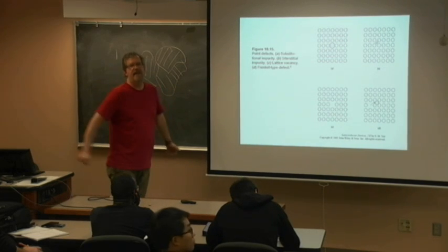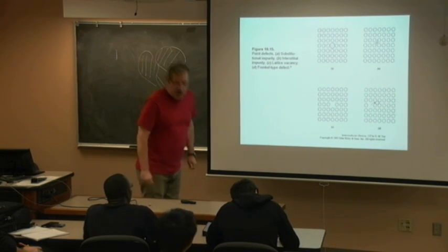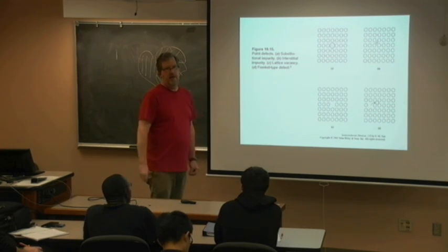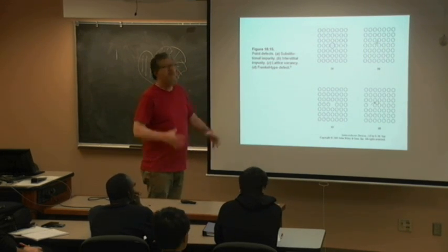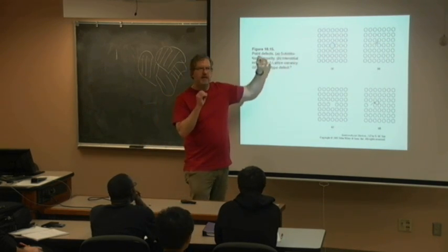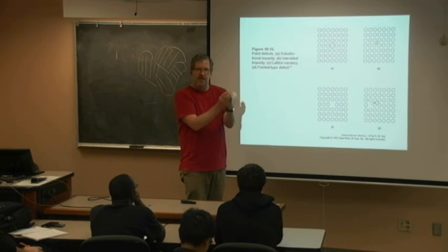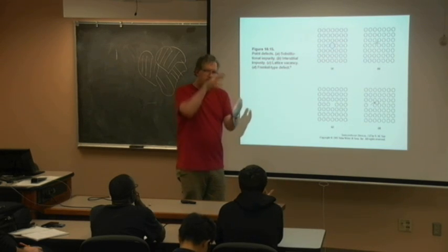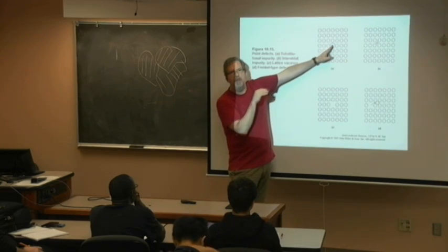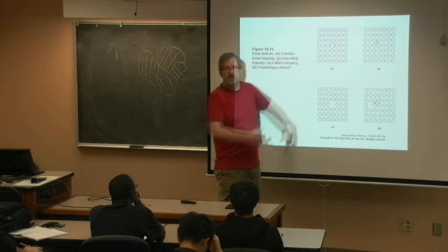Ahmed. The type of doping that we do later on is mostly substitution. It is only substitutional. If it's not going in substitutionally, it's not electrically activated. But how do you control that? Mother Nature wants to do that, because satisfying the 4 covalent bonds is what it wants to do. My Hope diamond wants to form a perfect crystal if I give it enough temperature, enough time. So if I introduce the dopants in a way where I give it enough temperature and time, it will pop in as this replacement impurity. It's going to replace the silicon atom.